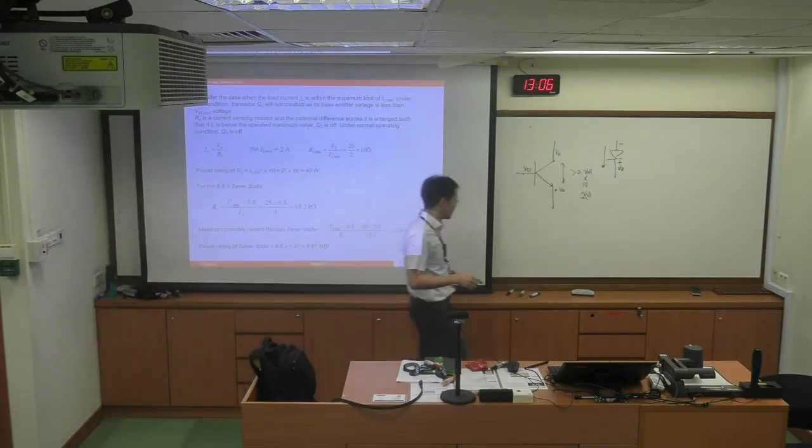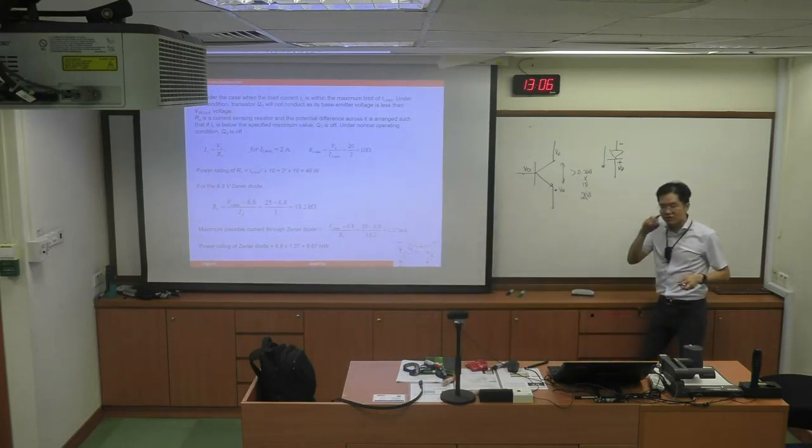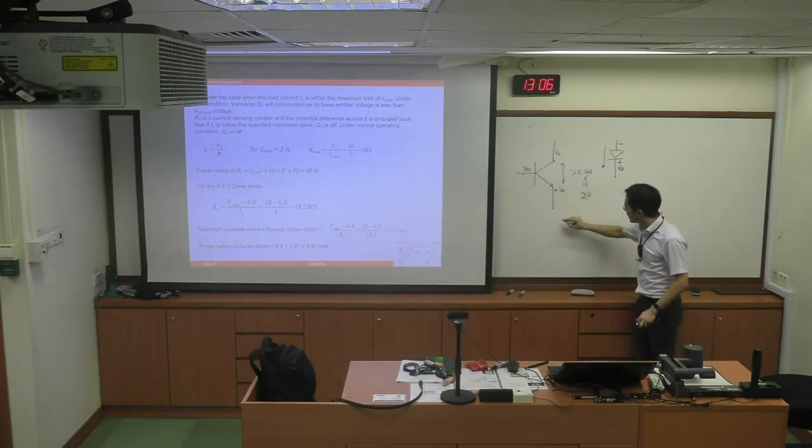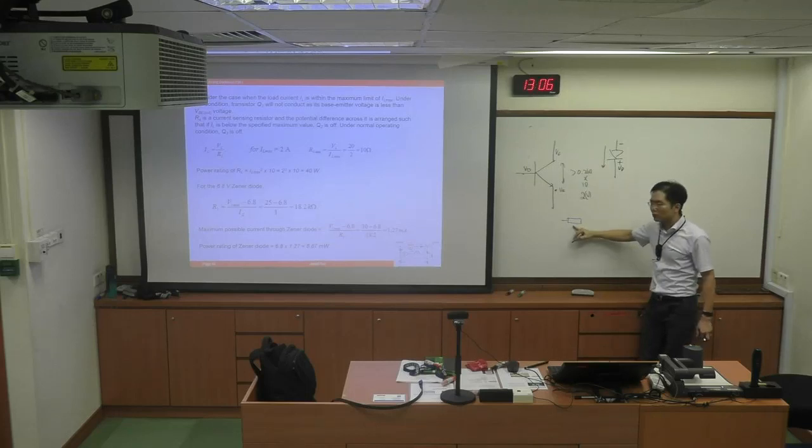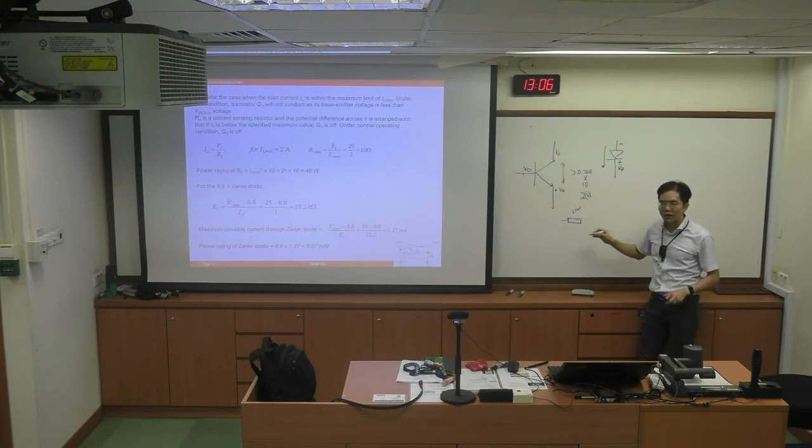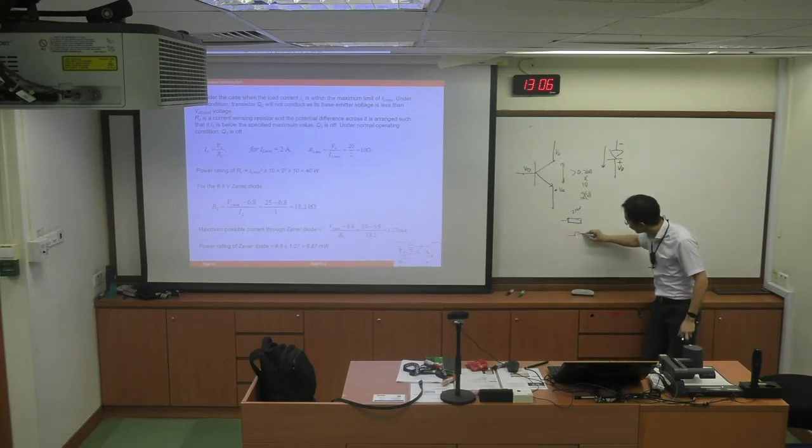So this is why in the lab sheet, which I will post tomorrow, you'll see that if the load resistance dissipates anything like 2-3 watts, then you should be using power resistors, which are physically bigger than the small nominal type of resistor you see with stripes like this.